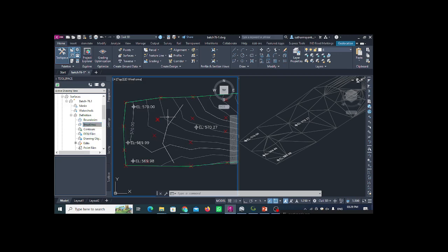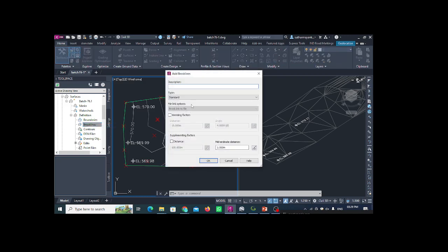So they make some contours very smooth and clear. So this contour line passes through the road and then they again join. Okay. So what we do? We add the break line. Just see the design here, how the line is and how the contour is, and after adding the break line, what will be the behavior?